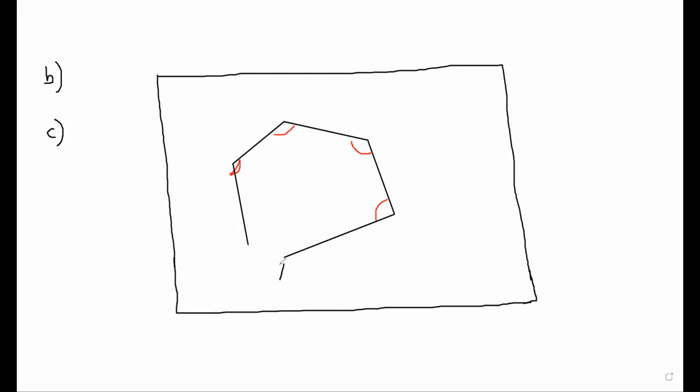You start with A, mark AB. Let's say AB is the line with the bearing. Then you mark angle B, corrected angle B, and go to C, go to D, go to E. When you mark point E and the length EA, you will not come to point A. So we mark it as A dash. It will be a smaller one. We don't know where this A dash lies. It can be anywhere, right?